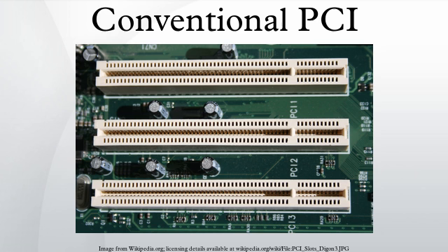To ensure compatibility with 32-bit PCI devices, it is forbidden to use a dual address cycle if not necessary, that is, if the high-order address bits are all 0. While the PCI bus transfers 32 bits per data phase, the initiator transmits 4 active-low byte enable signals indicating which 8-bit bytes are to be considered significant. In particular, a write must affect only the enabled bytes in the target PCI device. They are of little importance for memory reads, but I/O reads might have side effects. The PCI standard explicitly allows a data phase with no bytes enabled, which must behave as a no-op.